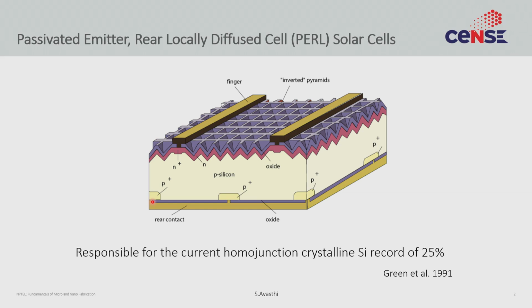We of course know how to make a p-n junction. We of course know how to select a substrate. So we start with the p-type substrate. We can probably diffuse an n-type region. We would notice that there are two diffusion layers, an n plus layer and an n layer, so there probably is gradation. There is a moderately doped diffusion, and then we need a second diffusion to do the highly doped diffusion. And of course those two are happening at different places. So we probably need to do lithography in the middle, right? So you need two lithography steps.